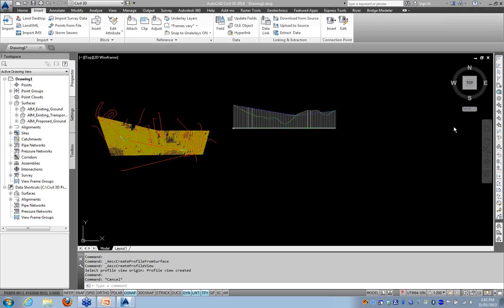Does the rail module lay out overhead lines? Presumably you're meaning overhead railway lines. It's only laying out alignments, so you can do whatever you like with the elevation in terms of the profile that the rail has. So if it goes up in the air, it goes up in the air, and that's fine. But the actual rail components, if you like, of Civil3D only deal with alignments.